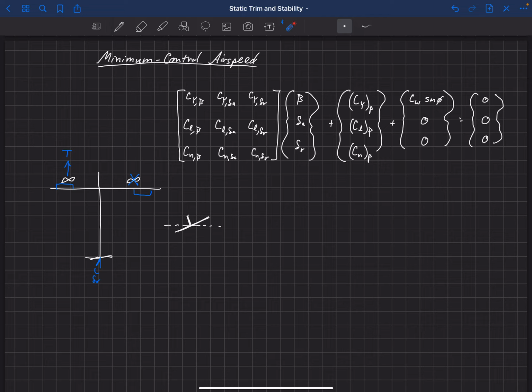At low velocities, that's when our yawing moments from an engine-out scenario, at probably full throttle here for takeoff, can be the greatest from our propulsion system if it's asymmetric. So this becomes a very important sizing condition, this takeoff and landing condition, where we're at full throttle and have one engine inoperative. It's one of the common sizing cases for a rudder, for how large the rudder needs to be so that it can trim out this case.